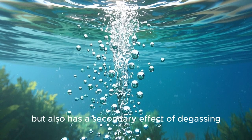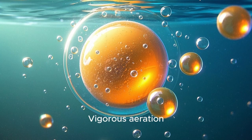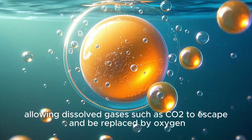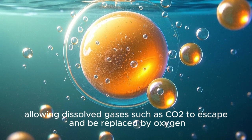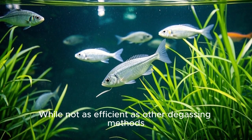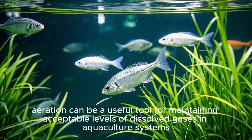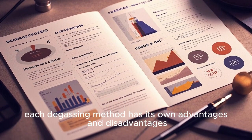The final method we are going to discuss is aeration, which is primarily used to add oxygen to the water, but also has a secondary effect of degassing. Vigorous aeration, such as that provided by diffusers or surface aerators, promotes gas exchange at the water surface, allowing dissolved gases such as CO2 to escape and be replaced by oxygen. While not as efficient as other degassing methods, aeration can be a useful tool for maintaining acceptable levels of dissolved gases in aquaculture systems. To summarize, each degassing method has its own advantages and disadvantages.